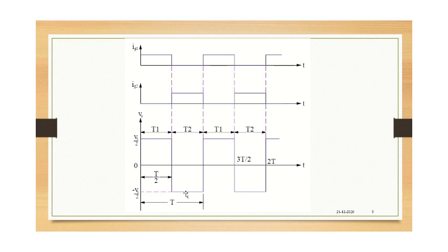So there will be a lot of harmonics, and that has to be removed to get a smooth curve, right? So that is about the basic operation of the single phase half bridge voltage source inverter. The mathematical expressions of this, that is the RMS output voltage, instantaneous output voltage and current, will be discussed in the next session.